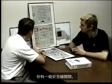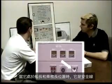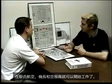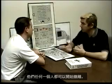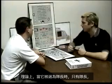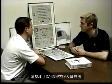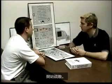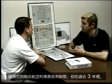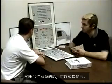Then you have a switch that's safety wired. It says captain and purser. When it's in the captain and purser position, which it's safety wired to at United, the captain and the flight attendant, either of them, can start the evacuation. Theoretically, when it was selected to captain only, it was basically wiring out the flight attendant from being able to initiate the evacuation. Although it's wired to captain and purser at United Airlines, for the last 3 years maintenance has deactivated the switch, so we couldn't even select captain if we wanted to.